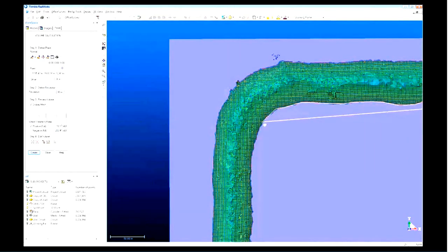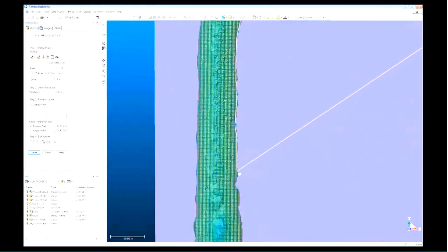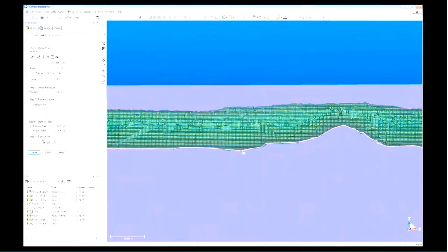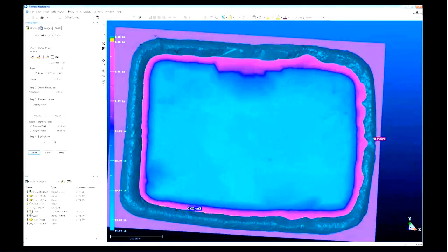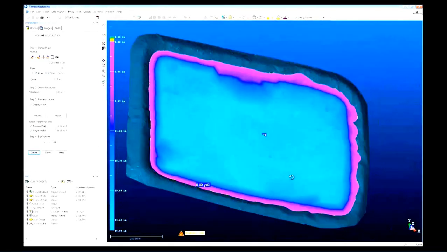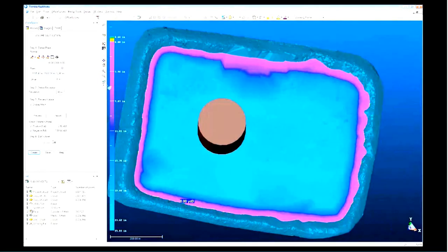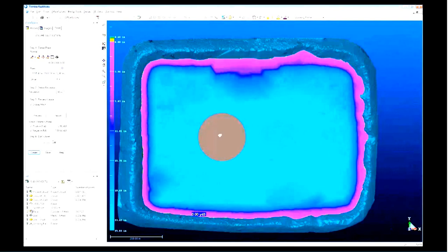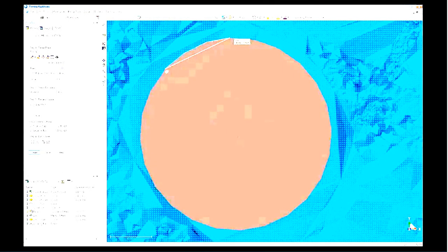So I'm just going to go through now and segment around the inside of the retaining wall where it intersects with that plane so I get the volume just inside there. Okay, just about done. All right, so now I'm keeping only the volume inside between the plane and that mesh. Just display my tank. I'm going to go and segment around and cut out that area from the volume if I want.